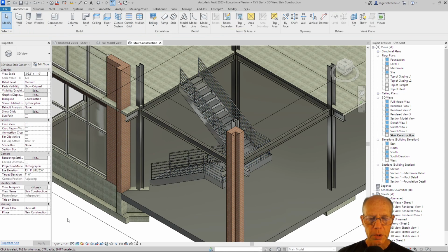So now we've constructed our first stairway system, and we're ready to take a look at adding some rails in along here. I also want to remind you or caution you that we'll find this being an issue. We may not be high enough for people to pass under this landing yet, so we may want to make adjustments, or you may want to make adjustments later on to that stairway. But suffice it to say, this is our brief introduction to creating stairways.